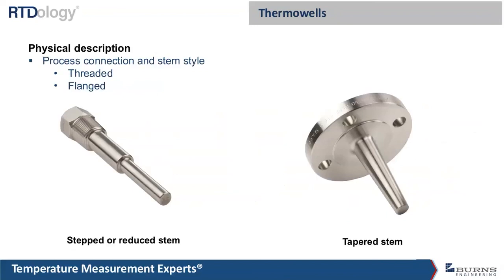There are lots of different process connections on Thermowells, and I'm just going to run through some of the more common types here. So we've got the threaded and then the ANSI pipe flange style. And we're showing these with a stepped or reduced tip stem on it. And this would be a tapered stem.